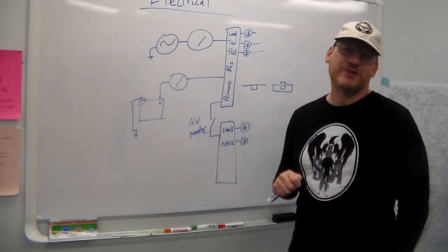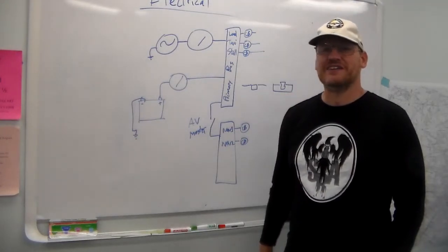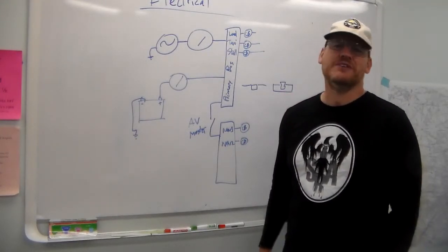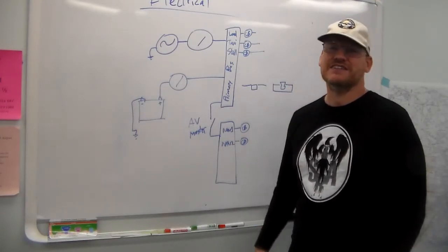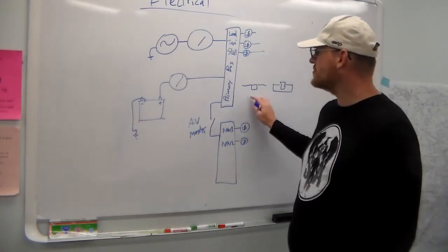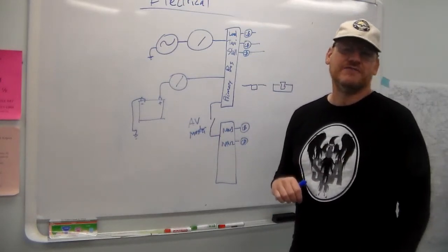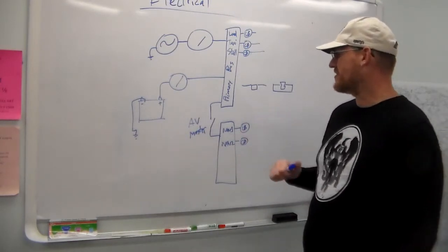I think that one is primarily so that flight instructors can torment their students by going, hey, how come your turn coordinator is not working? And they don't notice the big red flag on it that says, hey, I'm not getting any power right now. So those are the different kinds of breakers you might find in a typical aircraft.